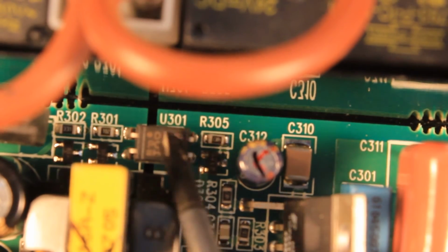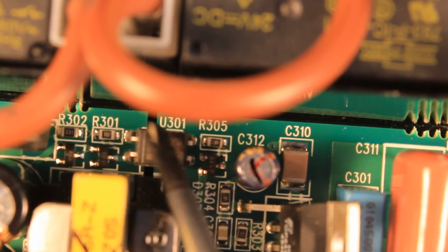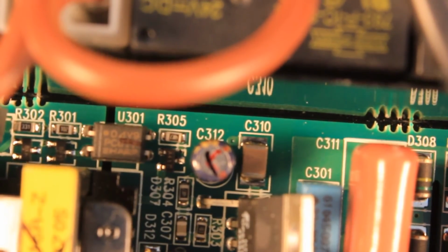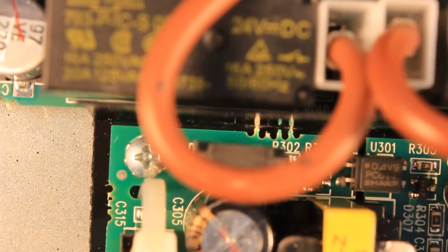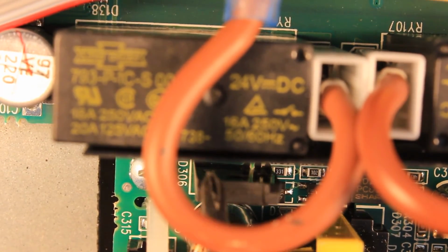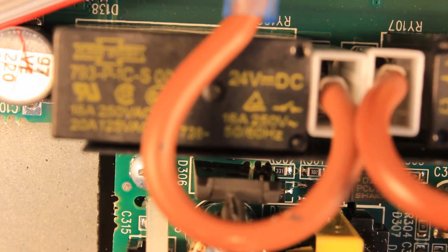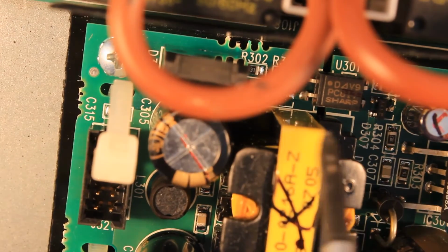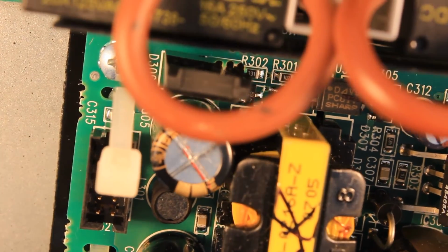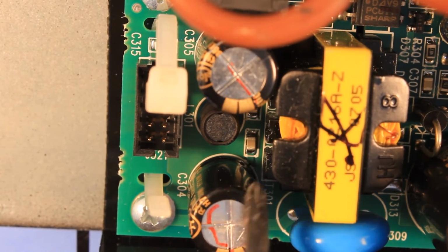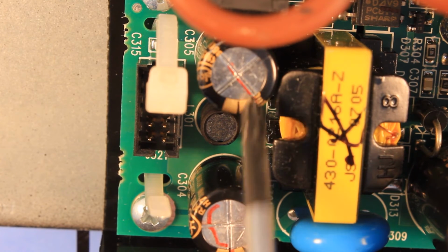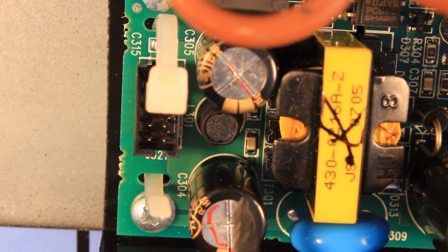Just as in the datasheet, they are using, of course, an optocoupler, and this is providing feedback for the circuit itself. And then this black thingy here is a double Schottky diode for actually making DC again out of the chopped DC going through the transformer. And then they are using 2 filter capacitors, and the filter capacitors are also Lelon branded and rated for 105 degrees C.